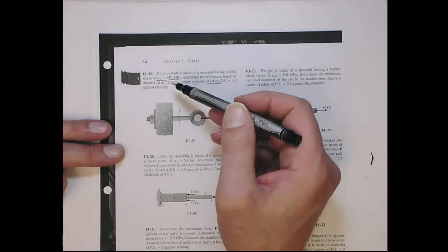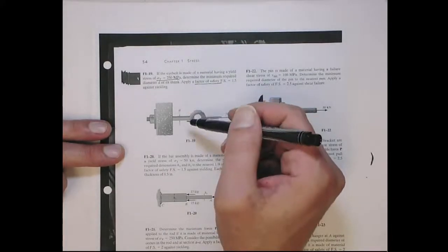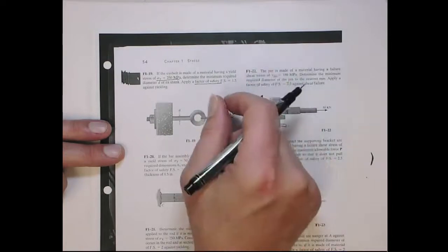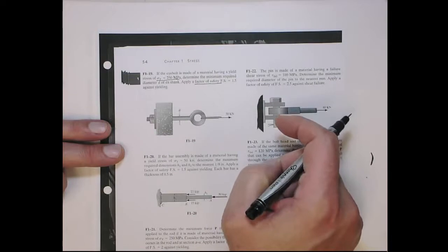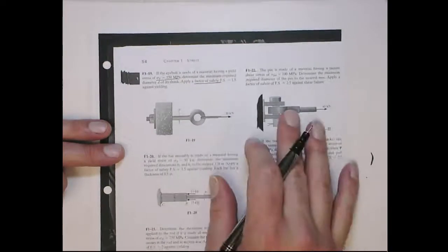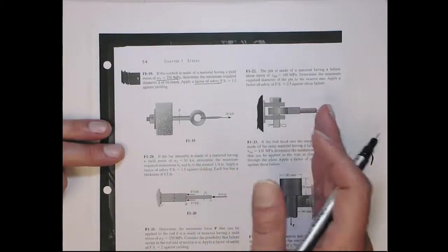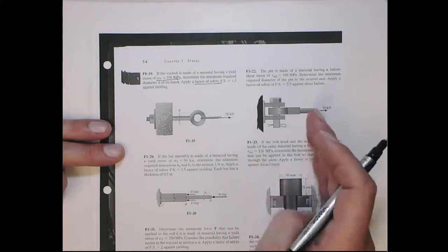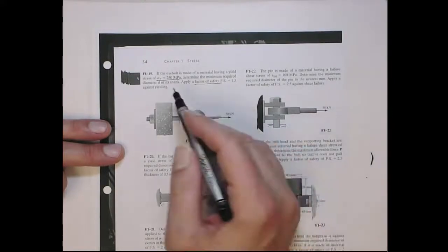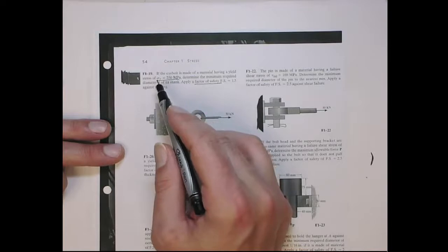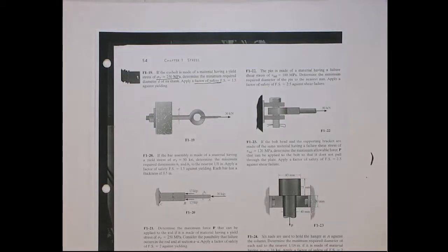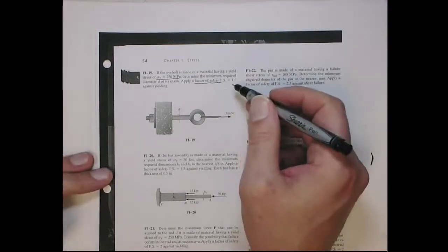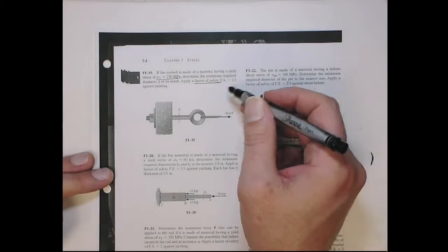So that means once the stress in this material exceeds 250 megapascals, it starts to behave plastically and stretches such that when you unload it, the deformation isn't recovered. We'll talk more about that in the next chapter. But basically you want to have the stress not exceed that. Not only that, it's specifying an additional factor of safety of 1.5 against yielding.